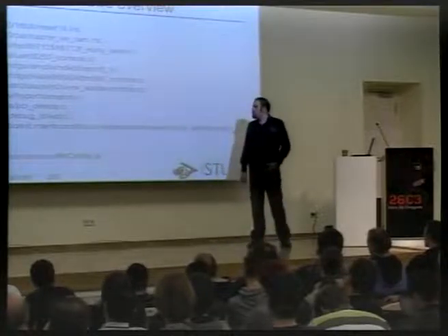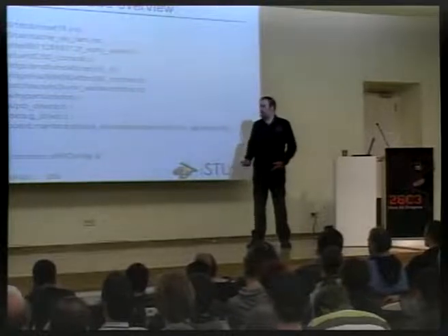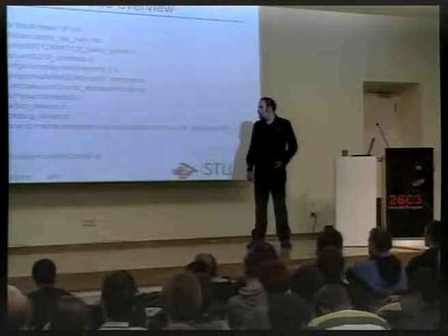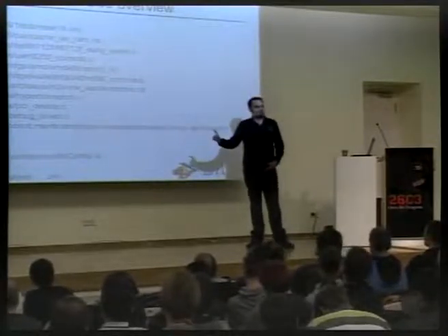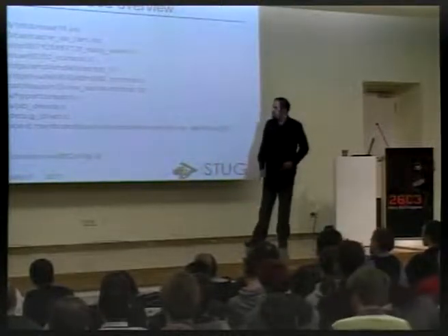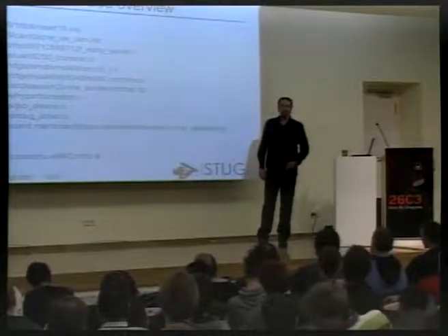fill with some settings for how coreboot is going to be built for this board. Number of PCI slots and stuff like that. So again, this was used only for the previous configuration method, but it's still necessary in some cases because kconfig isn't quite there for all the boards yet.